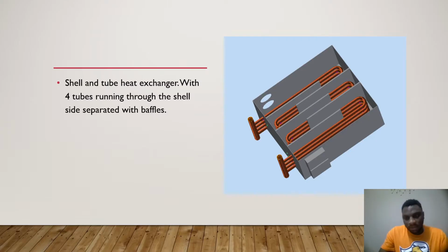So this is the design that I'll be talking about. This is shell and tube. See, the shell is this box right here, and then the tubes are going in horizontally through the shell, separated by some baffles.